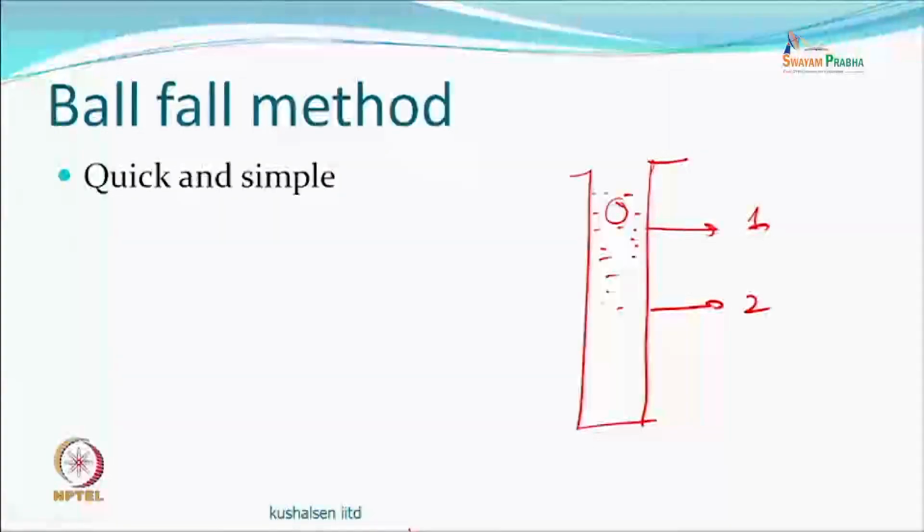So, in this situation, when you put this ball, as I said, initially it will start accelerating. You do not measure time when it is accelerating. In a standard equipment, people would have found that this type of ball, or this ball, or that ball, depending upon viscosity you use them, it will move down, accelerate, but after a certain point it would have attained the terminal velocity, and therefore you start measuring time.